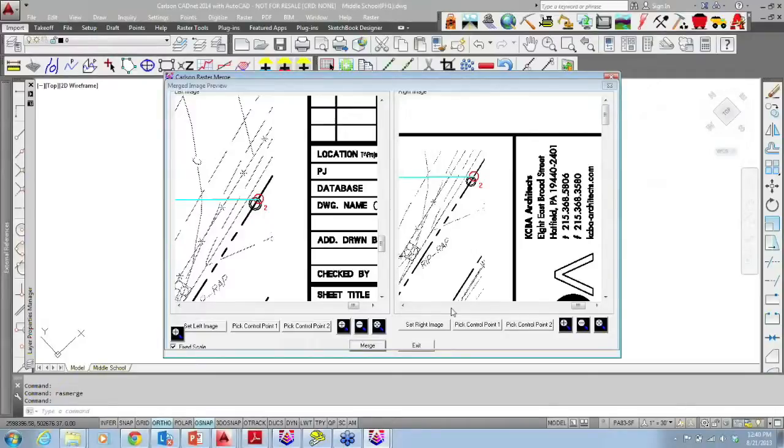save the plot as a PDF file, if you have Adobe loaded on your computer, it will store all the layers and all the line work in the PDF file, so that when you insert it with our command, insert PDF, you can use line work, and it will actually create the line work right from the PDF file, which is extremely handy. And you're right, you could then go right to doing sections, polylines to the cross sections, and skipping the step of digitizing. So I'm kind of curious why it's taking so long here.